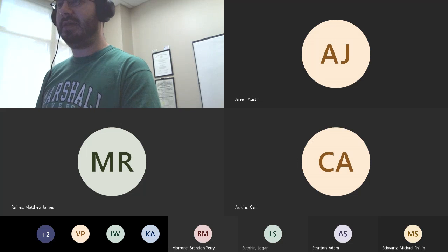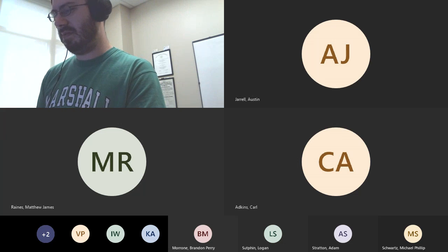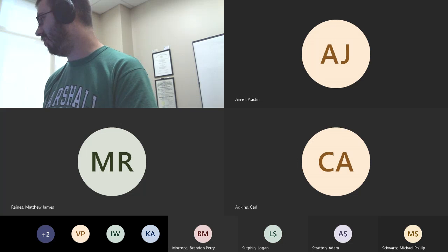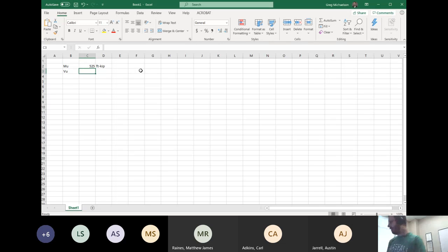Okay, so we have an MU of 525. We have VU of 53.2. Let me share this. All right, VU of 53.2 kips. And then we have CB of 1.67. So MU over CB is that many foot kips. And then LB for this problem, LB was 10 feet.